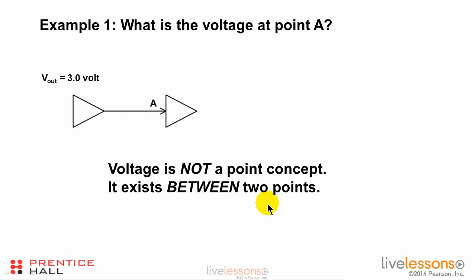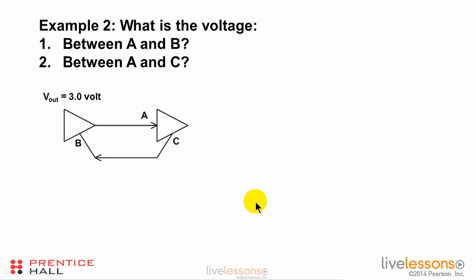We make that kind of statement all the time, and we sort of intuitively know what we mean. But that gets us into a lot of trouble sometimes, because we're being very careless about what the reference point is. The voltage is not measured at a point. It's measured between 2 points, and we need to be careful when we specify what those points are.